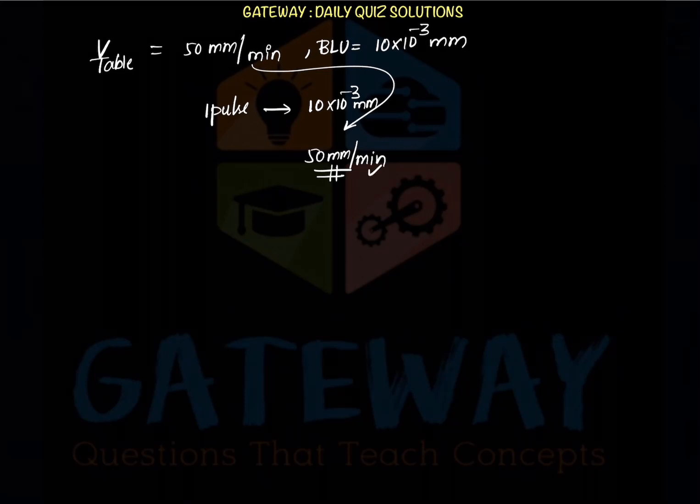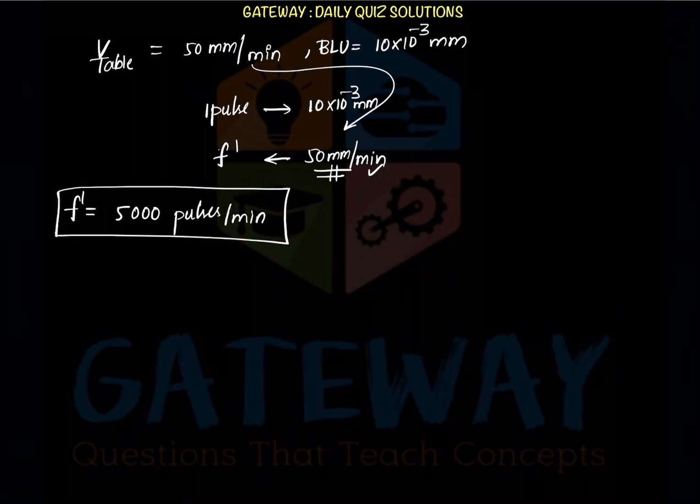Then for 50 mm of displacement in a minute, how many pulses should be generated in a minute? That will be our new F dash. With a cool mind, you understand, it will be very easy. So we get F dash as 5000 pulses per minute after calculation. Okay, this is our new frequency value.